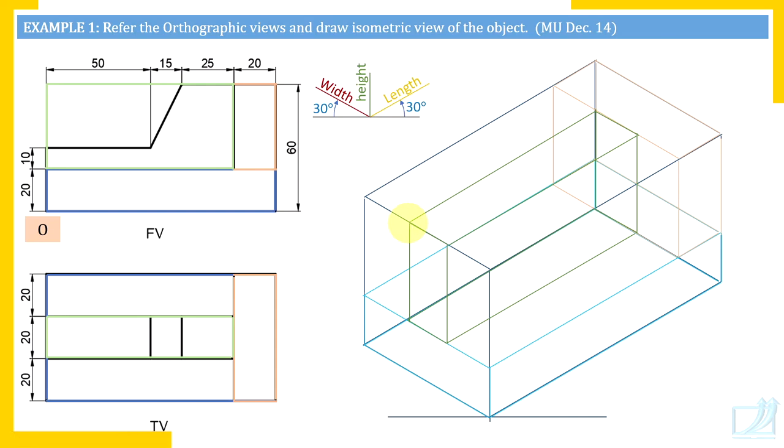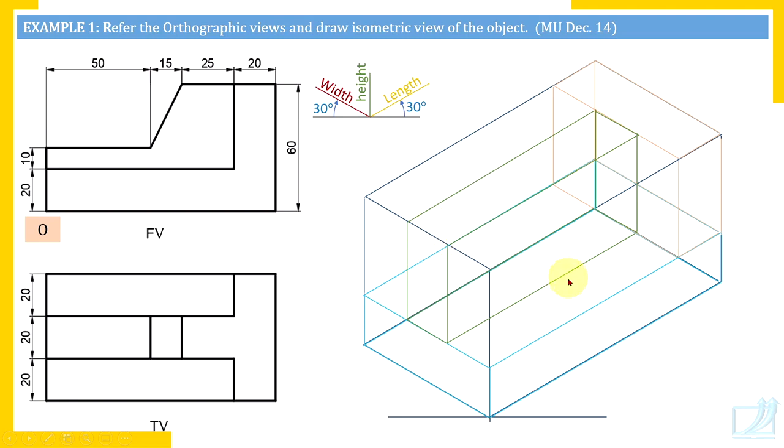So edges of front surfaces, edges of left side surfaces and edges of top surfaces we are going to make dark. So this is how we're able to complete the drawing. Now watch it. This is most important part of the drawing because these surfaces you are watching here are in different planes. So by drawing boxes for each and every part of the body, we are creating those planes. Now check here. Front surface of the base plate.